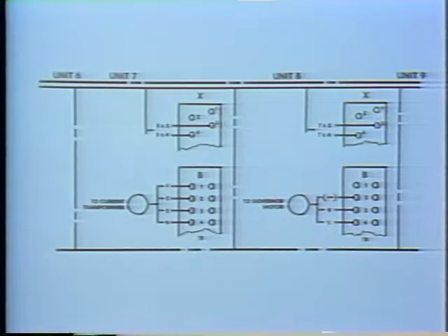This is an interconnection diagram. Interconnection diagrams are, in general, the same as connection diagrams. However, interconnection diagrams deal with wires or connections between separate units. Components are identified in the same way as connection diagram components. They're identified alphabetically from left to right and from top to bottom.